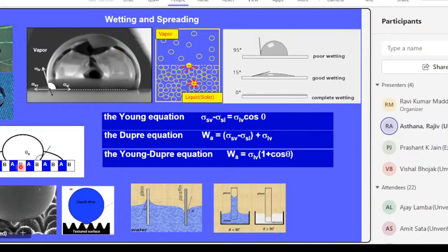So when you have, for example, steel, ordinary steel, plain carbon steel, you may have on the surface a region of pearlite, ferrite, austenite. So different chemical phases, how each of them will interact with the liquid is going to be a critical factor. So chemical inhomogeneity could affect interface. Surface roughness or any machining marks on the surface will affect the spreading of the liquid.